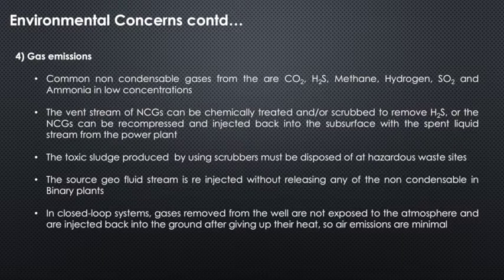Let's talk about the gas pollution. The vent steam from the cooling towers is filled with non-condensable gases such as ammonia, methane, and many other gases. They must be scrubbed and recompressed and then injected back into the subsurface during the reinjection. Also, care must be taken regarding the toxic sludge which is produced during scrubbing, and it must be disposed of at hazardous waste dumping sites.